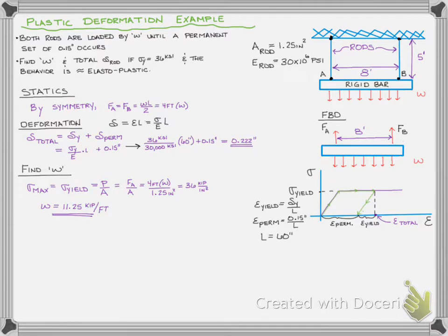So take a little time, study this. Please remember, if you sketch the elasto-plastic diagram, remind yourself: what's the total deformation? Where's the permanent set? Where's the elastic recovery? And that once we yield, we easily know what our stress is going to be. Then you can always jump in and solve these problems. Just keep all this in your tool belt so that you can use it later on.